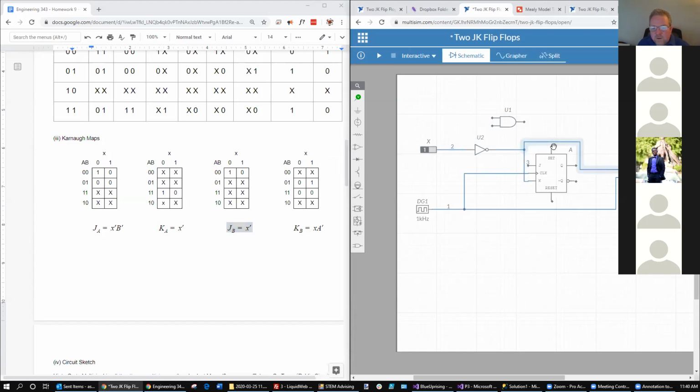There's that reset that I was telling you about. We're not going to wire these up right here, but the set basically turns Q equal to 1 and the reset turns it to 0. That's in case you want to clear out all the states and just have it starting home like 0, 0. So that way, when you power up the circuit, it just doesn't land in a random state. It starts, say, on the first floor of an elevator. All right, 2 down. And so now we got the AND gate right here.